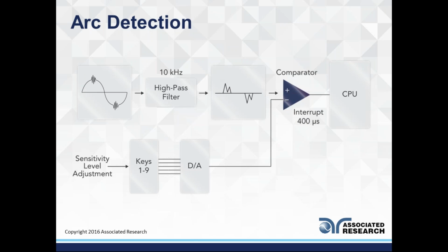So if you're trying to understand, am I getting less corona, more corona during the RD phase of your development, you will set your sensitivity to 1 or 9 depending on what type of information you want to get, and you'll be able to compare, did this arc get stronger or is it the same?